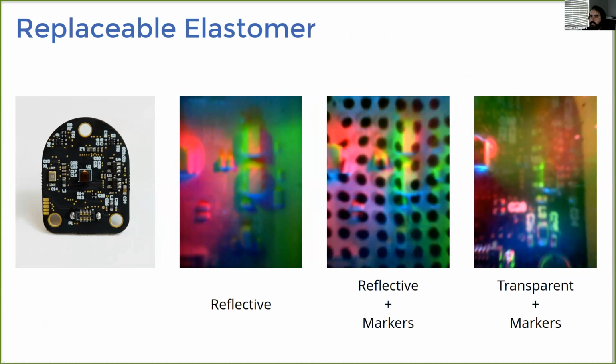And on the right, there is a transparent elastomer with markers, which are barely visible, unfortunately, in this picture, to control finger position during grasping. A little bit similar to what FingerVision does, if you're familiar with this other sensor. And in practice, this allows a lot of flexibility because you can have the equivalent of several sensors in one, depending on which elastomer you decide to mount.